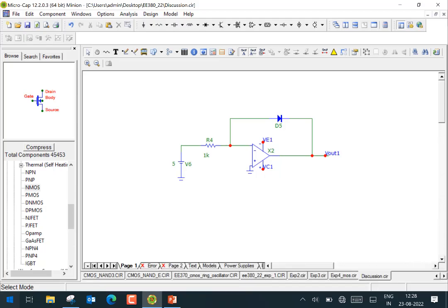All right. Sometimes in the lab, inadvertently, one ends up getting an interesting situation, which can be a learning opportunity for all of us, okay? So this is a circuit here. All of you have made this particular circuit in the lab. A resistor, a diode, and this. And we know that the current flowing from here will flow through the diode. And if the circuit has been made properly, I should get a negative voltage here, which is a negative diode drop, right?